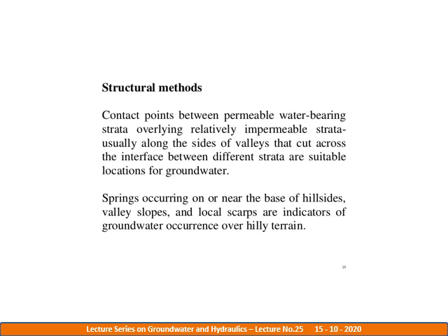Next is structural methods. Contact points between permeable water bearing strata overlying relatively impermeable strata along the sides of a valley that cuts across, and the interference between different strata, are suitable locations for groundwater.